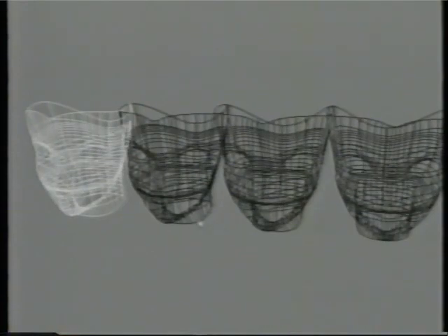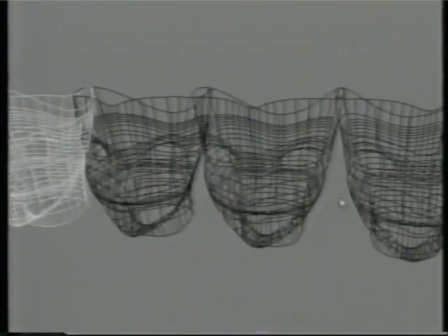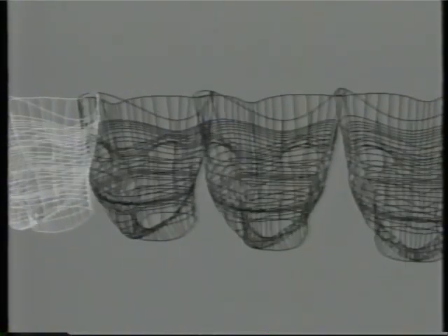Now if we look at all these together here, you can see that there are some subtle differences, and when texturing, some not so subtle differences. These three have all been assigned the same texture map. Non-uniform was left off because, like I said, that could look like any of them. And so the first one is chord length on the left, the middle is centripetal, and the far is uniform. And with a uniform you can tell how the curves were placed, and because there's lots of curves right around where the mouth is going in, you can see how many more squares you get.